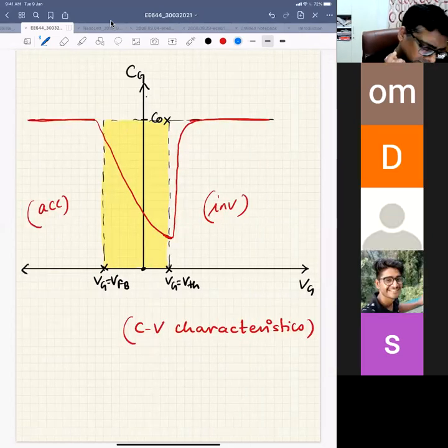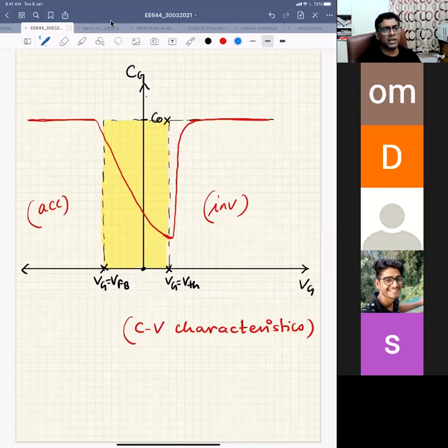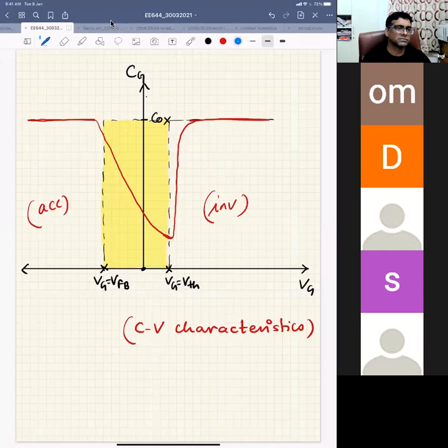So likewise for depletion region, we can say that our distance between the parallel plates is increasing because of depletion. Yeah, you could think that. This is like a depletion region, WD. Since in depletion region we assume that depletion approximation applies, there are no charges. So ultimately, the distance between the capacitance plates is increasing. The width of the insulating region is increasing, so this is same as a parallel plate: the distance between two plates is increasing because WD is changing, right?